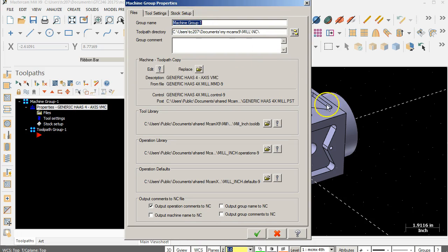With the 3-axis, we were mainly concerned with the ups and downs. Pretty much here we're going back to, and in the description I called this, 2.5 axis to position. All right, so we're going to rotate this block to a certain position, and the advantage here is that we're going to get to 4 sides of our cube in one setup.